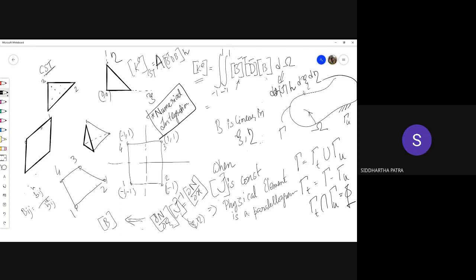We could not even consider the bilinear quadrilateral element, which is linear in xi and linear in eta, hence bilinear, if we are strictly into direct integration. That's why we need numerical integration, and when we employ numerical integration, we can go even further than this. We can consider higher order elements. So I'll discuss the higher order elements first, and then we'll go to numerical integration.